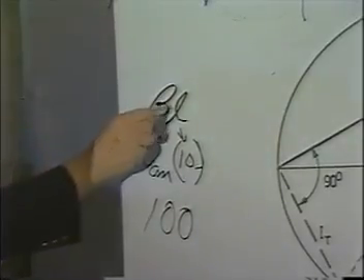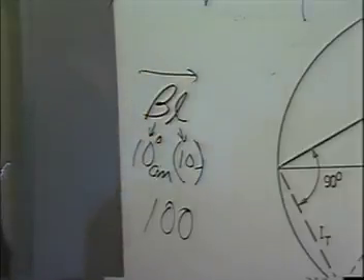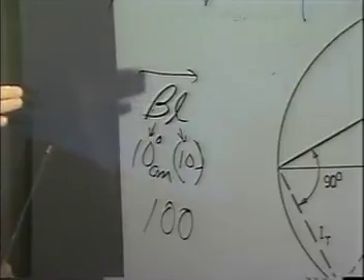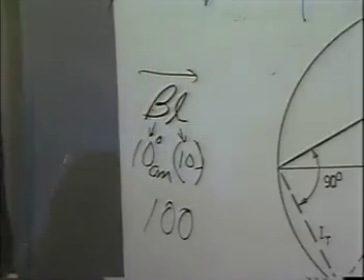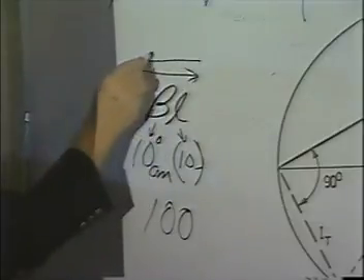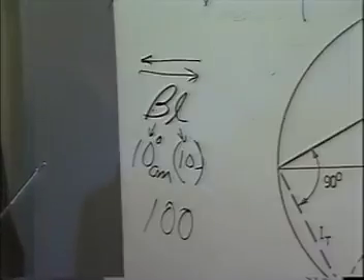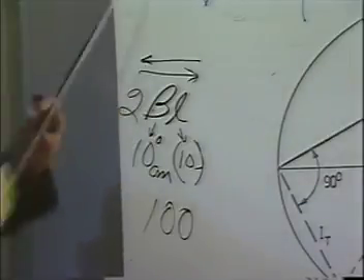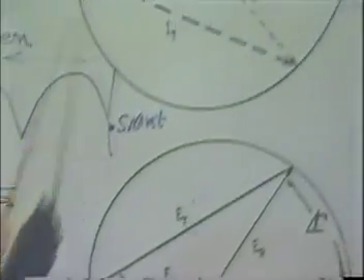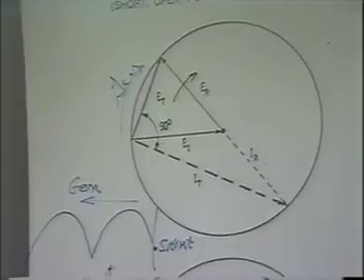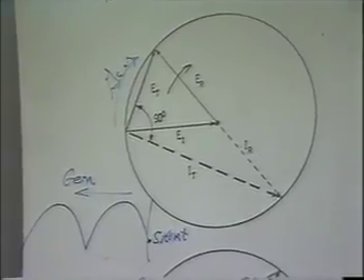Now this beta L is in one direction. Beta, change in phase in one direction. L is the length in one direction, right? But in our case, not only do we have a wave traveling to the right, but we have a wave traveling to the left. So you're going to find very shortly by mathematical equation that this has to be 2 beta L. So this thing here has to rotate at twice the speed in order for this chart to represent this.